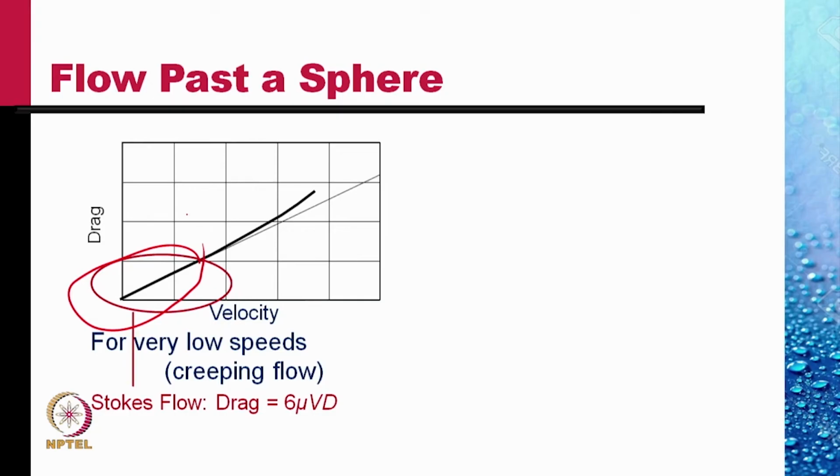Typically, that would mean that for a fluid like water, the velocities would be in micrometers per second, and the dimensions of the bodies would also be that low. Only very fine dust particles, microbes, and such biological entities have a Reynolds number as low as that while moving.